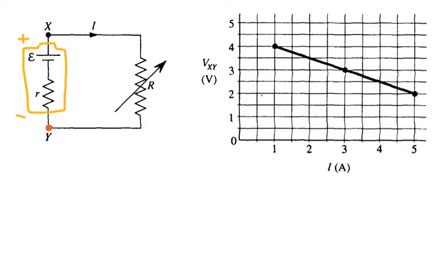So I'm going to start by writing the equation for Ohm's law. Your total voltage, EMF, minus the voltage dropped on the first resistor, the potentiometer, so it's the current through the circuit and the resistance of the potentiometer, and minus the voltage dropped on the internal resistance, which I'm going to call lowercase r. So all of the voltage has to be equal to 0.